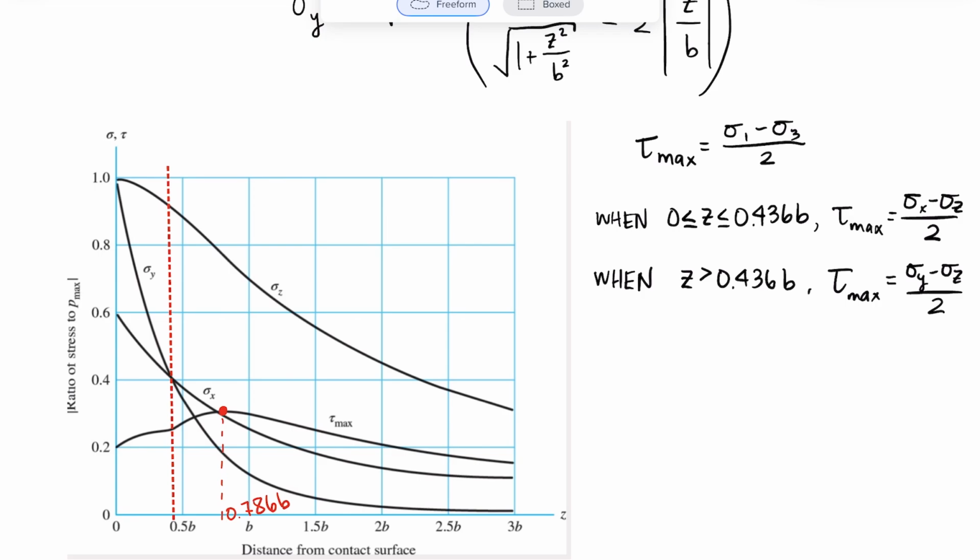But it is more random, more stochastic, because if you're thinking about a rolling sphere or cylinder, those Hertzian contact stresses are going to be repeated each time you have a rotation, and so that leads to surface fatigue failure.